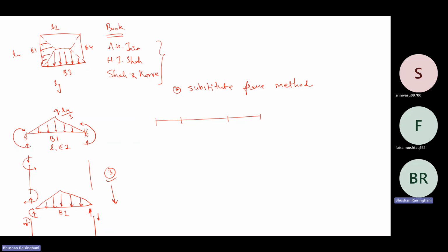Okay, so if you put alternate spans, what will happen is that this will bend like this, but this will bend like this. So end spans are always hinged. Okay, so it is not fixed. So this will create a negative bending moment for it. So the behavior will be negative. Now the same span, if I keep and load here,